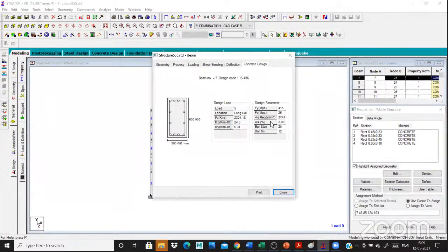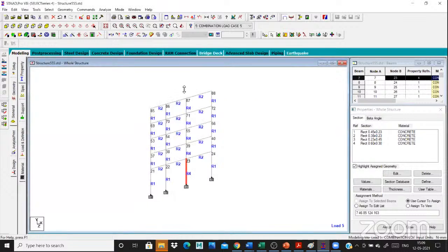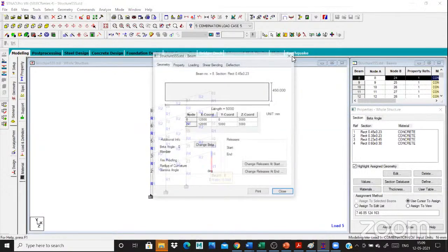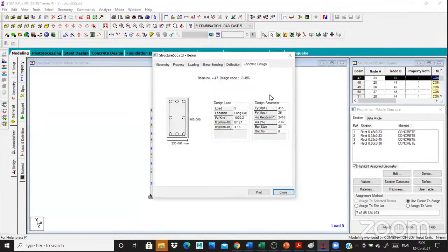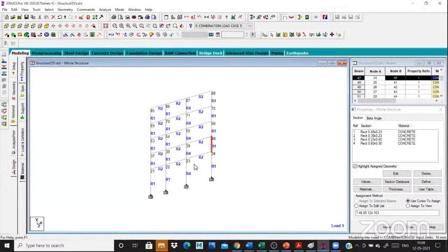The load is 2000 kilonewton, but the column size is smaller. That is the problem. This is a method to redesign all the structures. That is the condition. Okay. You go for 300, but sometimes you will provide 300 by 450, and it will be designed. Increase the column depth. That is a condition. But if not for architecture purposes, you can increase the width also. So okay, now it's clear how to redesign the structure.